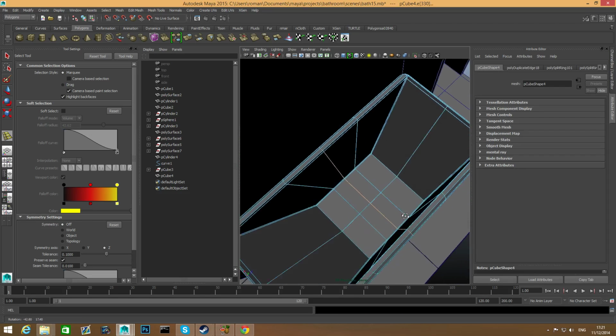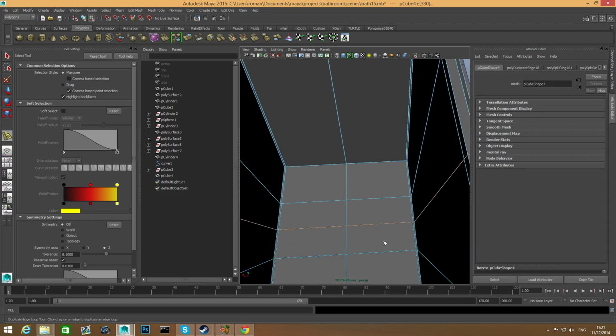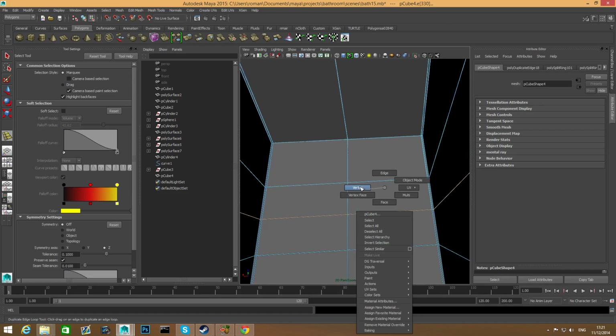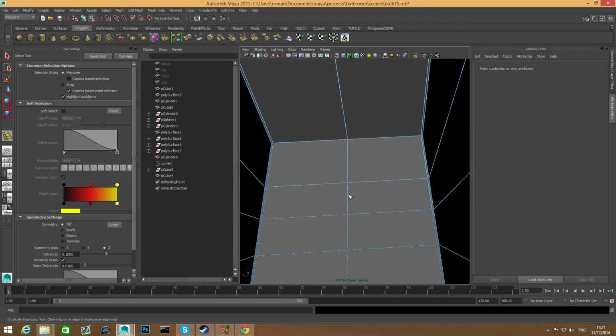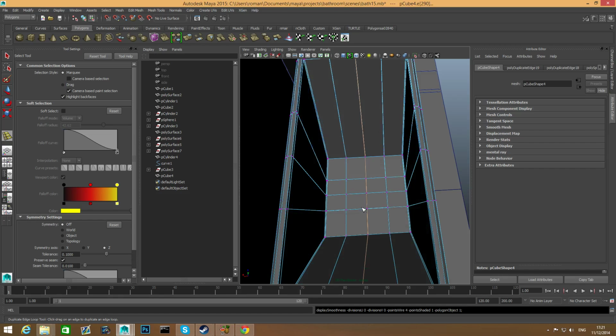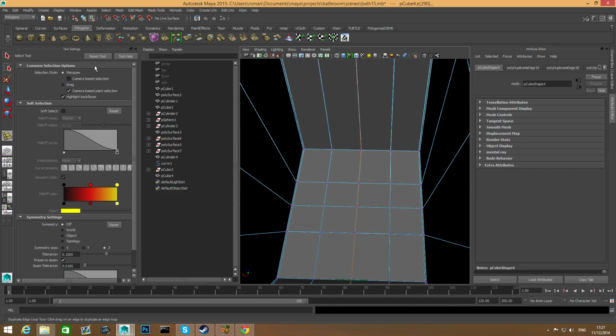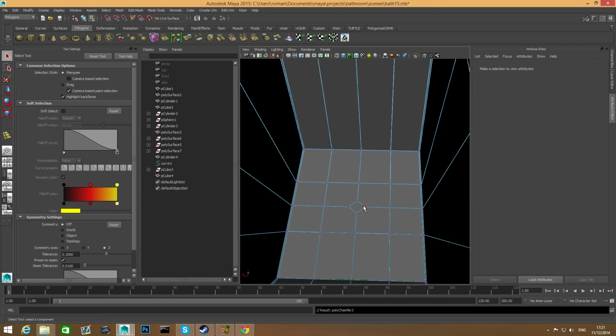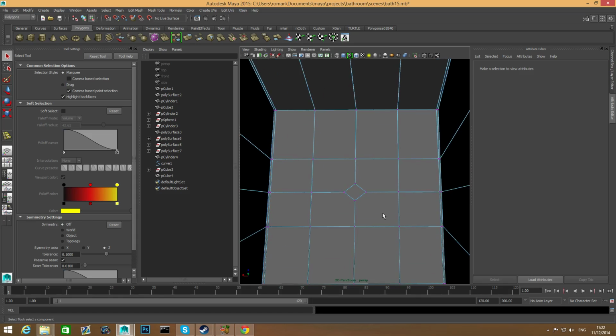So only here. This is what I am looking for, and I can even add 2 more edge loops here to maintain this. Let's take a look. 3, still curved, looking good. Can grab this edge, shift right click, chamfer vertex, and you already know the procedure.